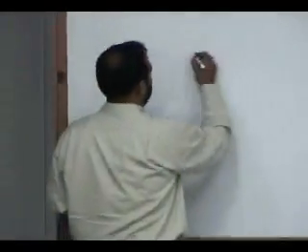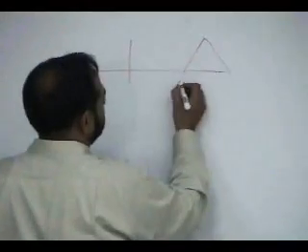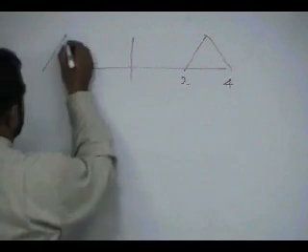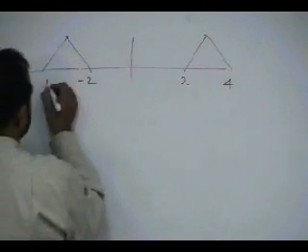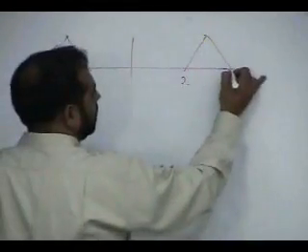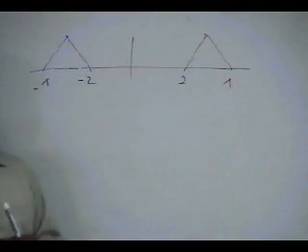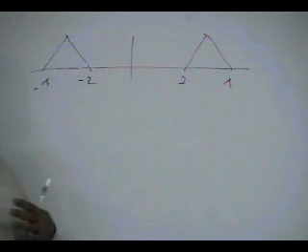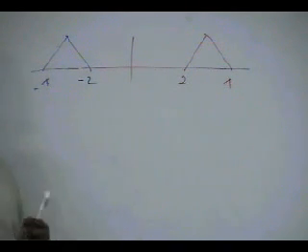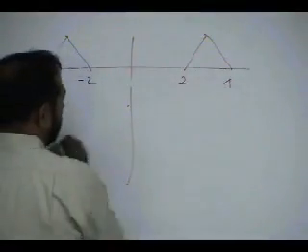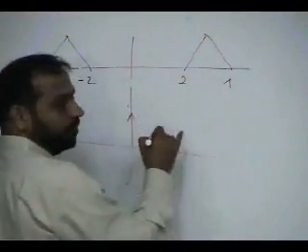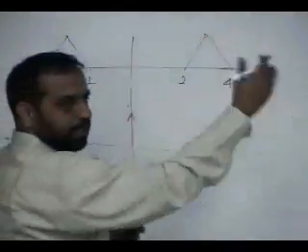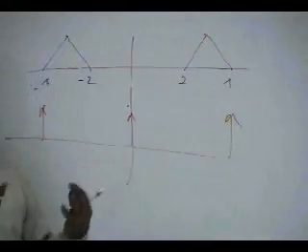So I give you a simple example. For example, here is a signal which runs from 2 to 4 kilohertz. Okay, and maybe it has a negative part, 2 to 4 kilohertz. Now this requires me to sample it at 8. I say I'll not sample it at 8, I'll sample it at 4. So let's try to sample it at 4. What will happen? If I sample it at 4, I make a copy of it at 0, then I make a copy of it at 4, I make a copy at -4, at 8 and -8 and like that. So I make copies.